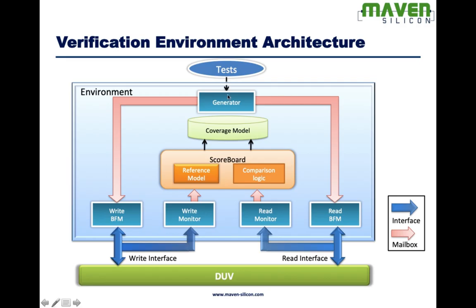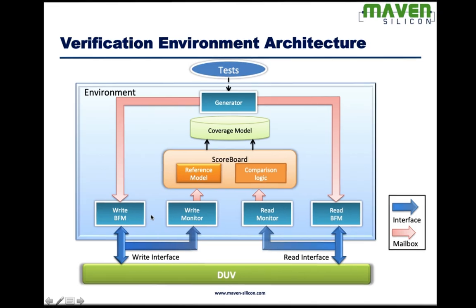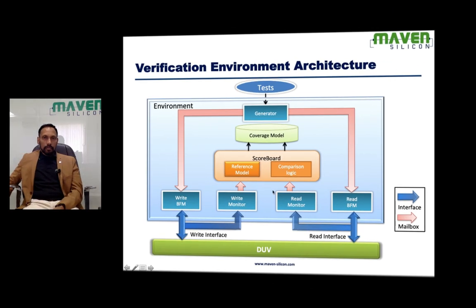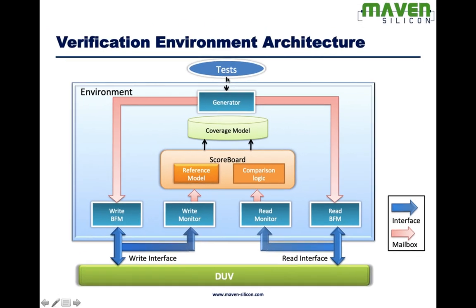And the environment has all the test bench components like generator, driver, monitor, and for each interface we create a driver and monitor. You need to remember this framework. And the monitors will be connected with the scoreboard. On top of the environment, the test case writers will be writing test cases, so there will be multiple test cases.